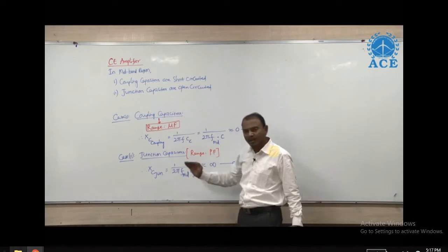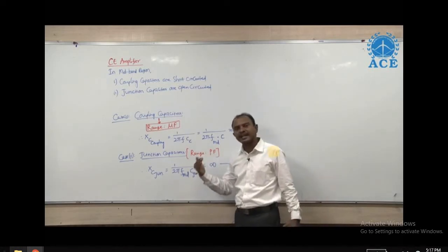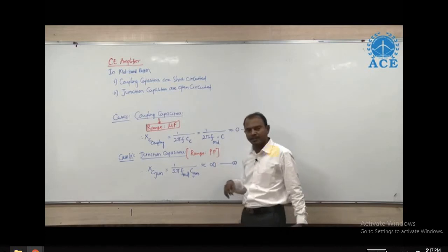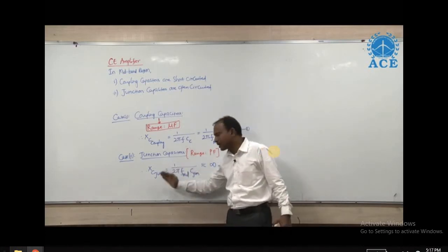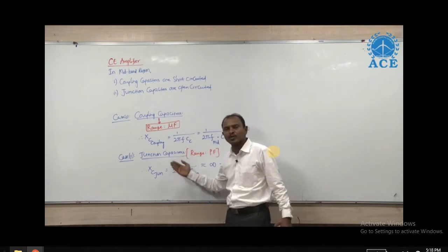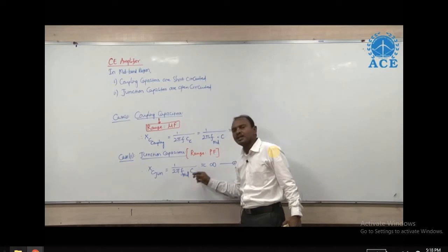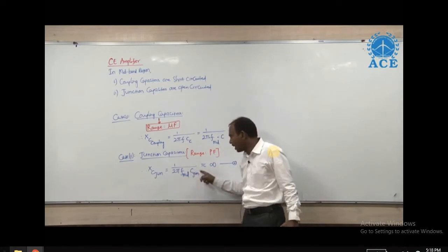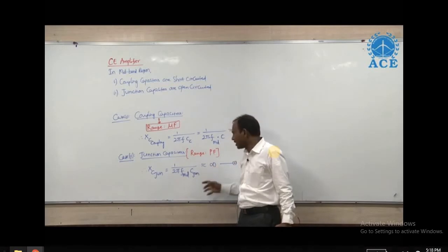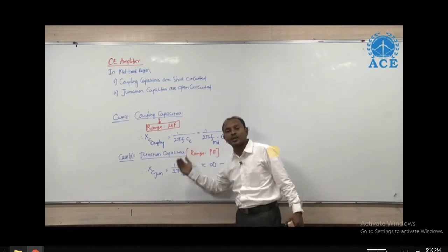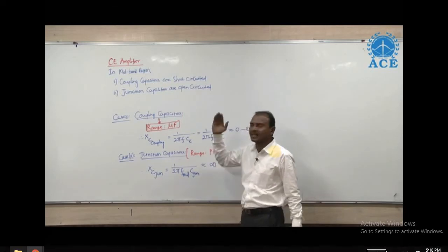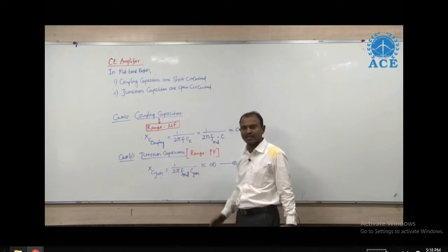On the other hand, coming to junction capacitors, generally, junction capacitors are the internal capacitors of the device, and their range is generally of the order of picofarads. As a result, at mid frequencies, consider the reactive impedance of junction capacitors again as 1/(2πFC). Mid frequencies are generally of the order of a few kilohertz to a few hundreds of kilohertz, and the junction capacitance value is of the order of 10 power minus 12 farads, that is picofarads. Altogether, the total denominator value is of the order of 10 power minus 9, and as a result, the effective reactive impedance of the junction capacitance at mid frequencies is more or less infinite, or very high. As a result, we can conclude that junction capacitors will act like open circuits at mid frequencies. So, option C is correct.